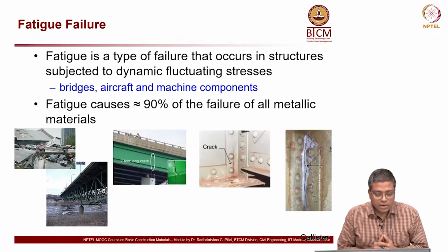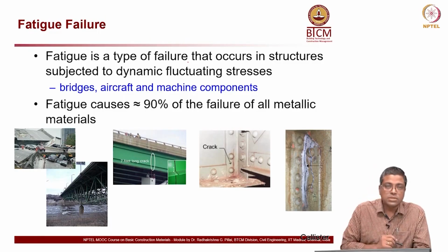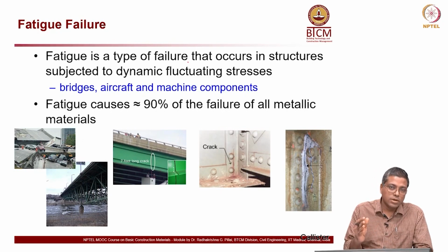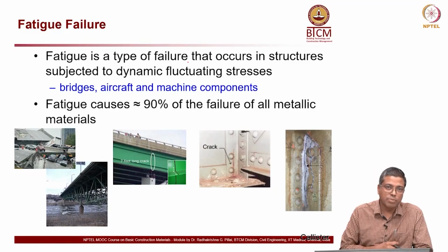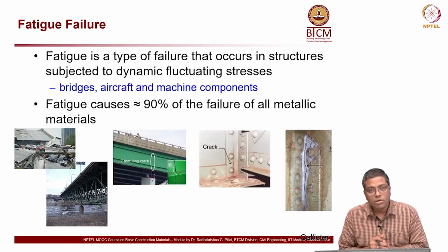Now, another phenomenon is fatigue failure. What is fatigue? It is a type of failure that occurs in structures subjected to dynamic fluctuating stresses. It means the stress might change from tension to compression, compression to tension back. These kinds of fluctuations might happen in the stresses, and that leads to a failure phenomenon called fatigue failure,